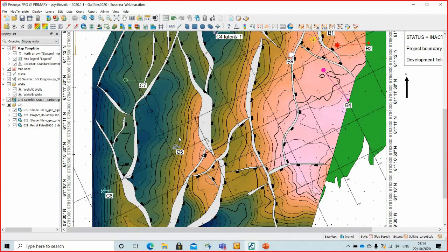Now, I obviously want to highlight that within this fault block and this fault block only, because I don't have any evidence of contact levels in different fault blocks, and I also maybe have contact levels at different depths at, say, a fault block around here. Currently my contour increments are being displayed at 20 meter intervals, so I obviously need to first of all display a single contour level.